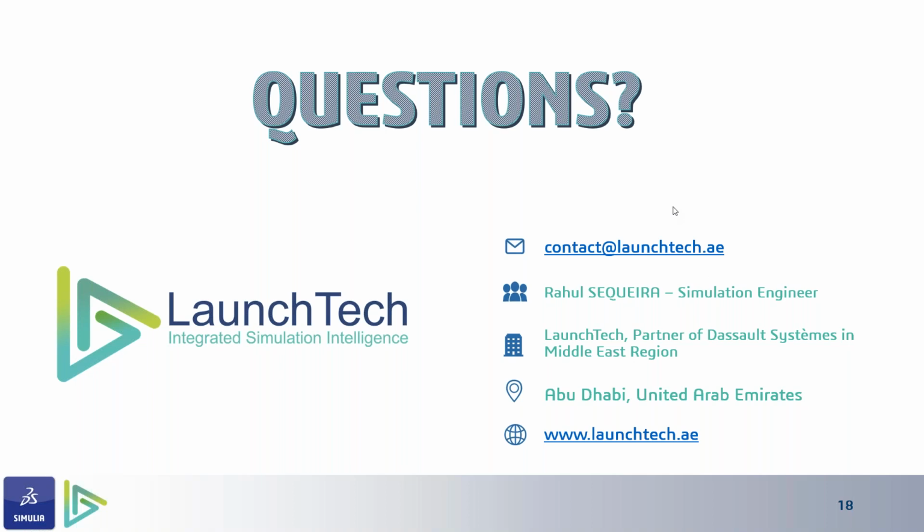I have another question. Does Abaqus include hardening soil models or any soil models? That's a good question. In terms of elasticity, you can model it, but with plasticity you might have to use the user subroutines option to model those soil capabilities in plastic models. There might be plugins available, but I would generally recommend using the subroutines in order to model plasticity of soil-based materials.